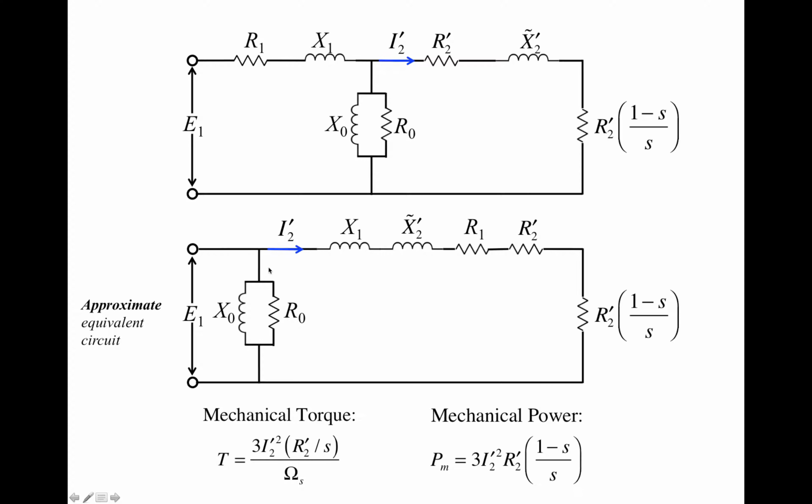For small machines, for small induction machines, less than 5 horsepowers, you cannot do this simplification. The error could be quite large. But for the induction machines used in wind turbines, this simplification introduces negligible errors, right? So by just moving this part of the circuit to the front of the entire circuit, you can make the calculation a lot easier, and the error introduced is less than 10%, right?